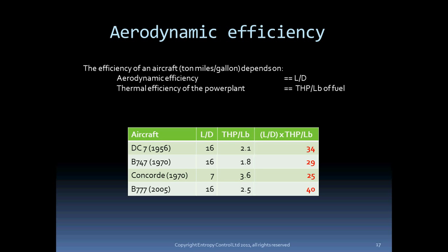The really interesting entry in the table above is Concorde. Concorde had a low cruise lift drag ratio of only about 7 due to supersonic drag. But the high speed creates lots of horsepower per pound of thrust, leading to high engine efficiency, almost making up for the high drag. This kind of back-of-the-envelope calculation seems to indicate that the Concorde should have been almost as economic as the 747. But the sad fact is that many effects kept the aircraft operating well away from its optimum profile most of the time, and that, coupled with high purchase and operating costs, doomed the project from the beginning.